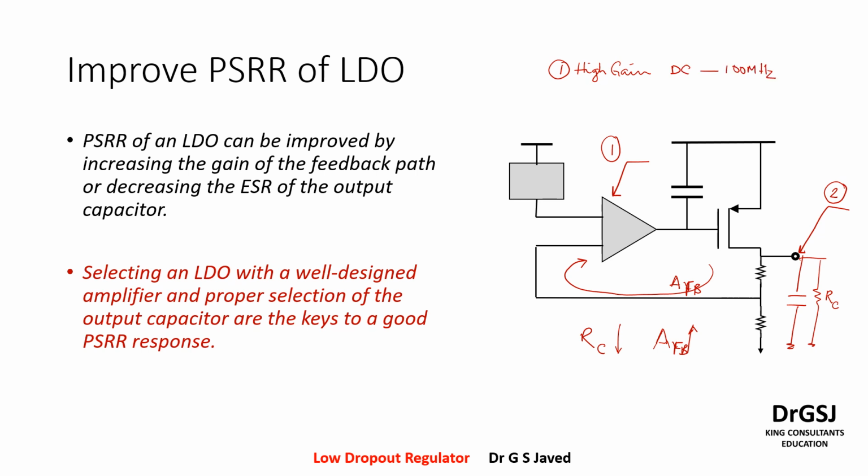You have to look at the bandwidth, or the 3 dB bandwidth, which is expected to be a little larger than 100 megahertz, such that you see better results. Ideally, you could look at say 500 megahertz to give you a much better response. And the third one, which is typical of all things, is how much gain margin and phase margin is present in this design. So these are the key elements that you have to answer.